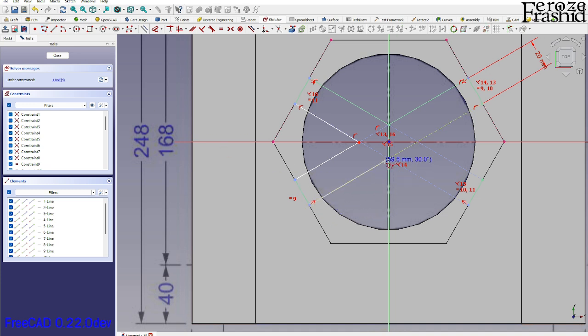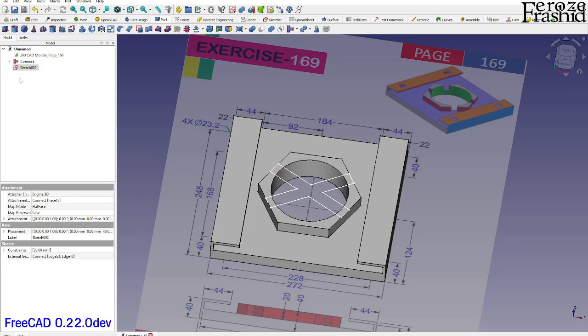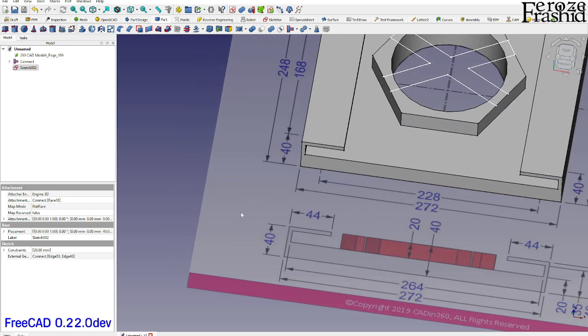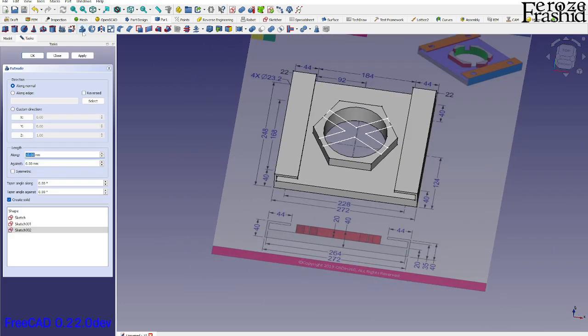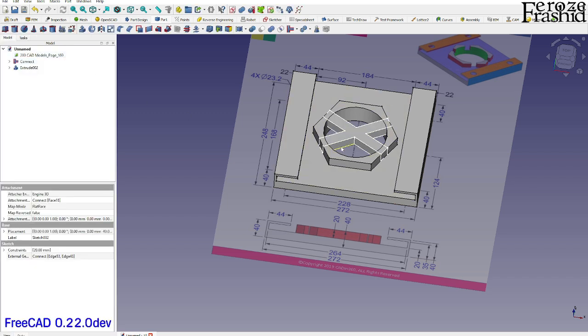As we were making these lines, let's go ahead and finish the outside of it. Okay, I want to place it on this line as well. Do the same, and that's now a closed wire sketch. Okay, this one, let's go ahead and take it down for 20 millimeter. So it would be an extrusion for 20 millimeter, and reverse, and hit apply and close.